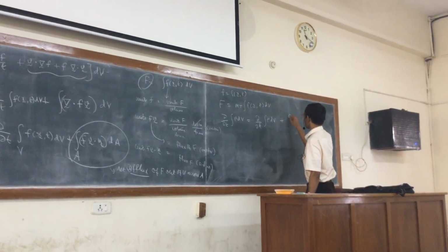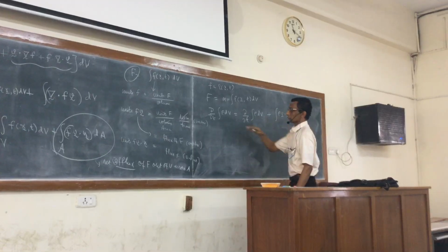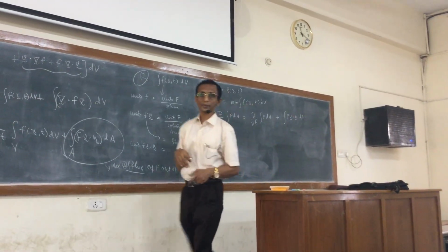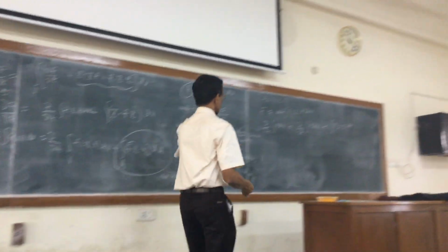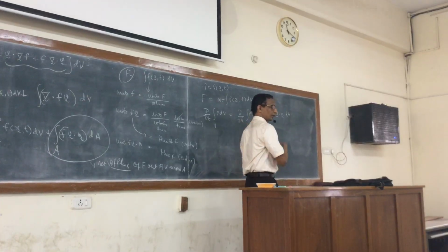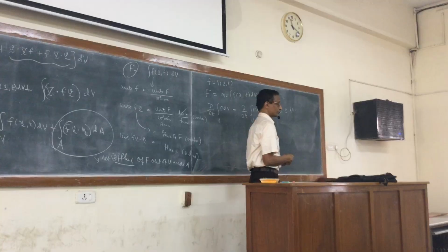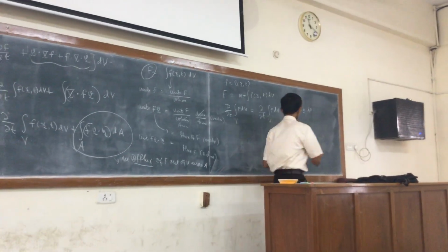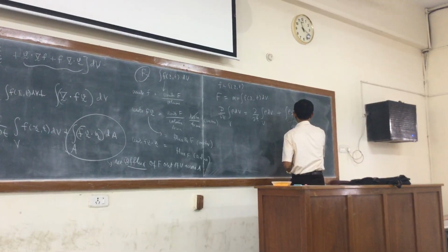Plus, the derivative of change of mass, the substantial derivative, is equal to the time rate of change of mass within the volume of fluid, the spatial derivative, plus the net efflux of mass.